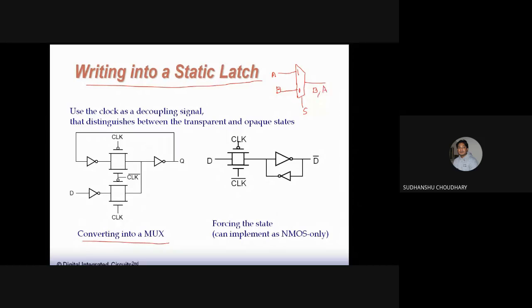So based on this multiplexer, one can think about implementing a multiplexer latch using transmission gates. So these are transmission gates over here. Utilizing the transmission gates and the static CMOS inverter, one can think of making a multiplexer based latch. That is a MUX based latch.